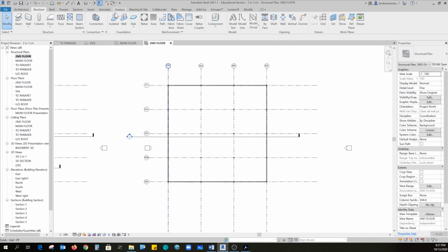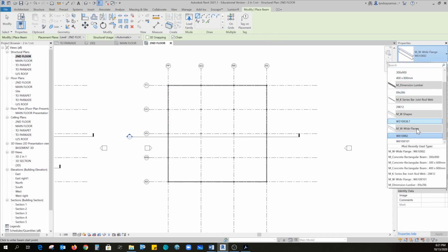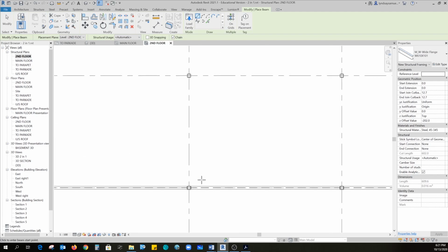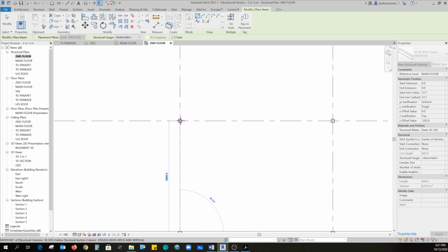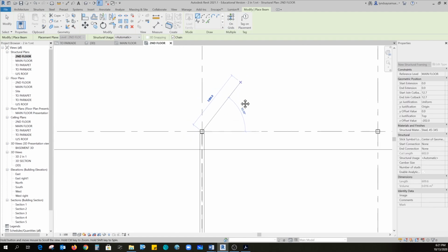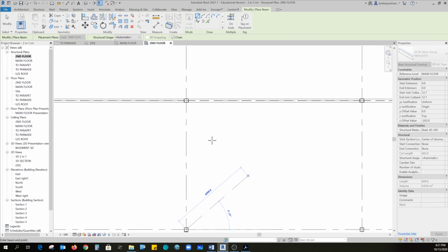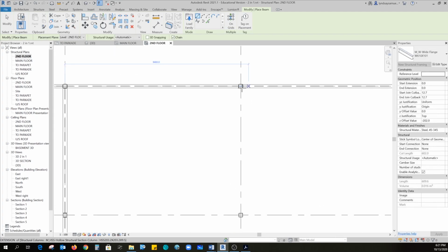So all I have to do is go back to the beam, switch the size to the larger one, 610 by 101. The setting for Z offset's the same. And these guys go down the middle, bigger, because there's going to be joists sitting on it on both sides. So it needs to be stronger than the ones that are on the outside.